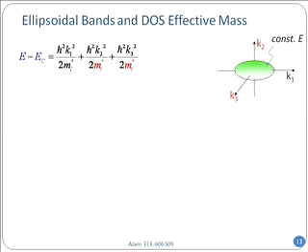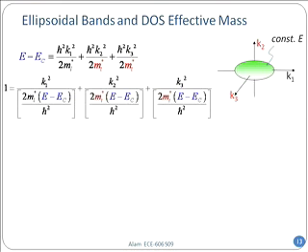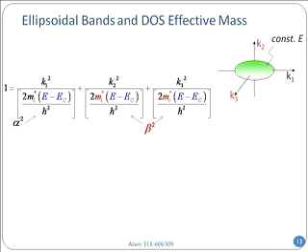Now, I also have, in the longitudinal side, you see this has 3 axes. In the longitudinal side, I have ml, and on the transverse side, I have the effective mass mt. Now, in general, this doesn't have to be the case. You could have 3 different masses in 3 different directions. For this particular material, germanium and silicon, 2 just happen to be the same.